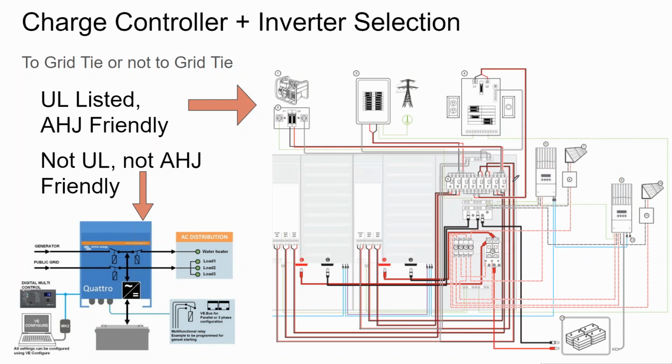And so that's where I see, when you go for an inverter that is listed for grid connection, and not only for being charged from the grid, but also outflowing onto the grid, they're generally smaller than what it takes to power an entire house. And so then you want to get two of them, and hey, there's nothing wrong with two inverters. It's doubly redundant. So if one fails, you have the other one there to operate while you fix the first defective inverter. So it's not that there's anything wrong with double redundancy.